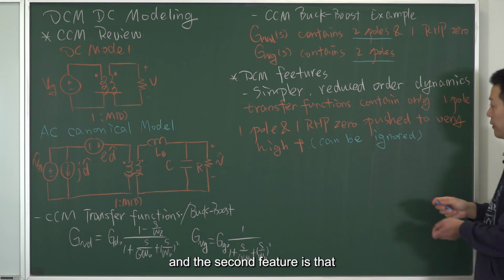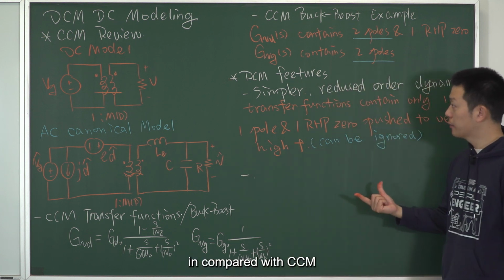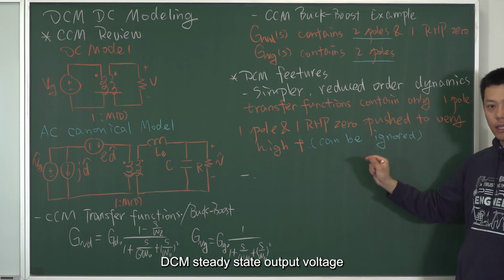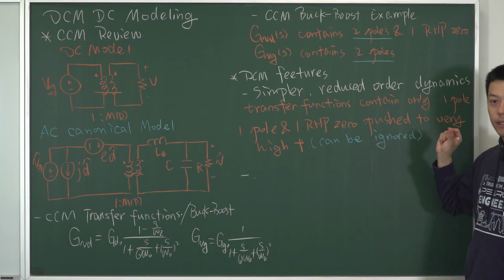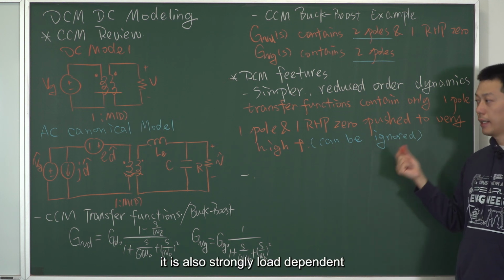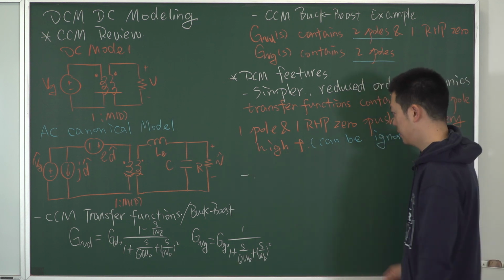And the second feature is that, compared with CCM, DCM's steady state output voltage is not only dependent on duty cycle, it is also strongly load dependent.